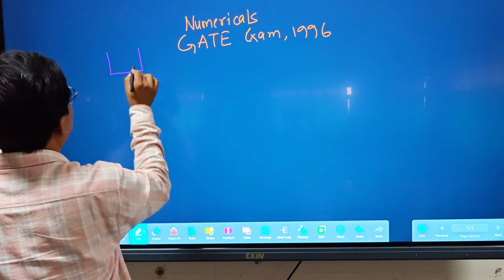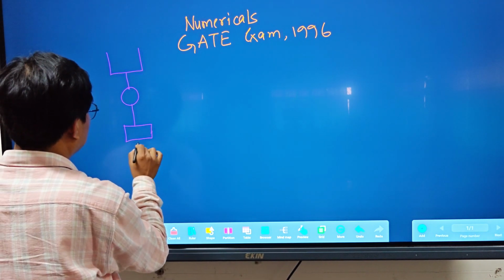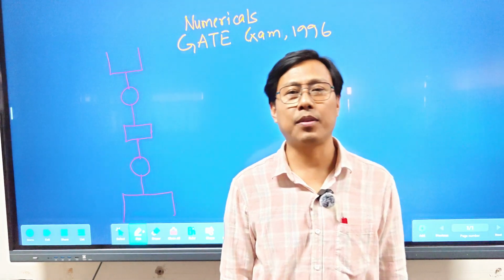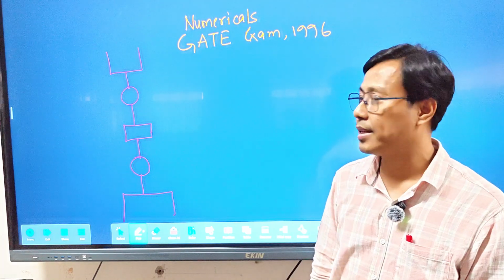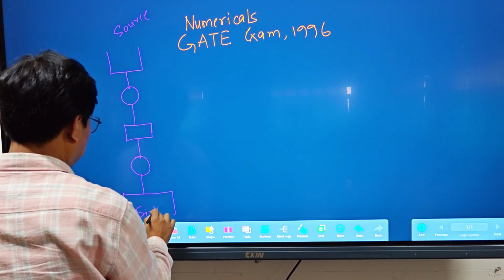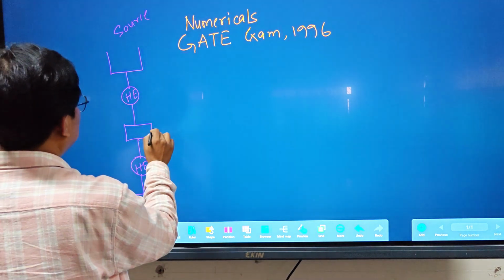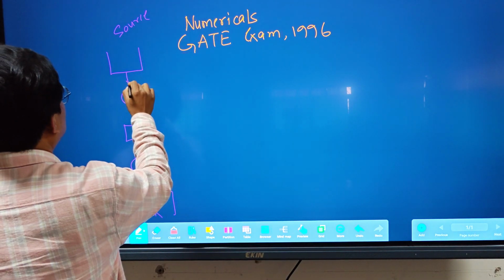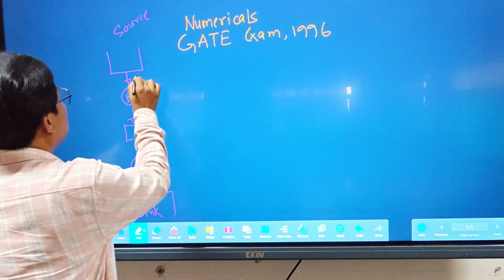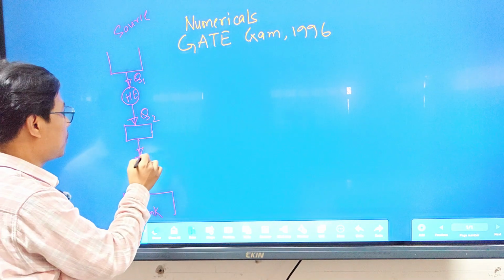In this block diagram, we'll have two heat engines. This particular system is having two heat engines or two heat cycles. This is the source, this is the sink. Clear? This is the first heat engine, this is the second heat engine, and this is the heat exchanger. So we have first heat addition and heat rejected, and here heat addition and heat rejected. Here the heat received is Q1, the heat rejected is Q2, and whatever heat is rejected will come to the second heat engine.